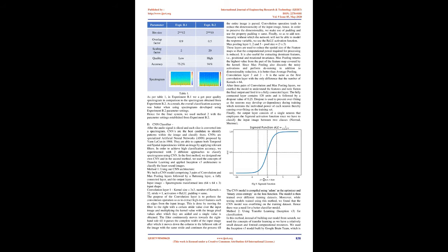Furthermore, the output of the STFT is complex valued, and even though the spectrum is a vector, the STFT output is a matrix. As a result, we cannot directly visualize it. Instead, STFTs are visualized using log spectra, 20 log10 |X_h(k)|. This 2D log spectra is visualized via our spectrogram.